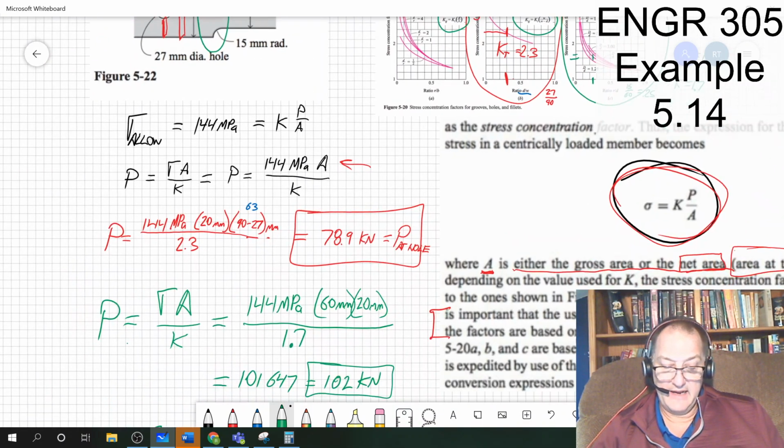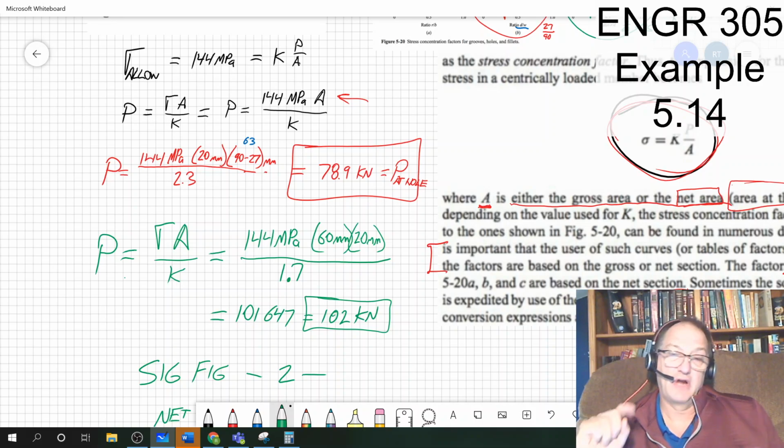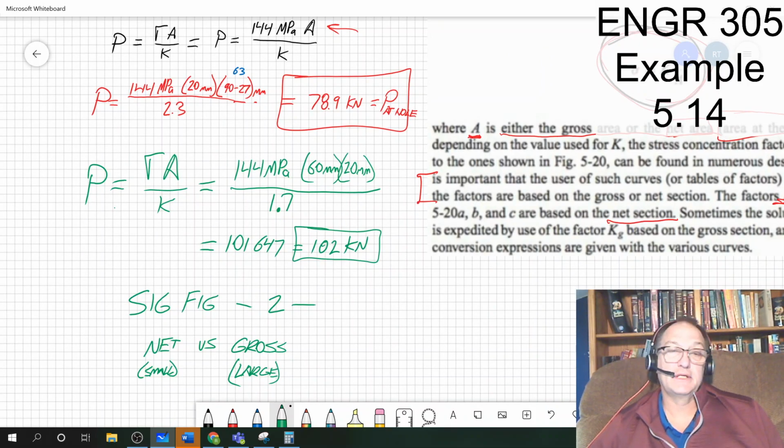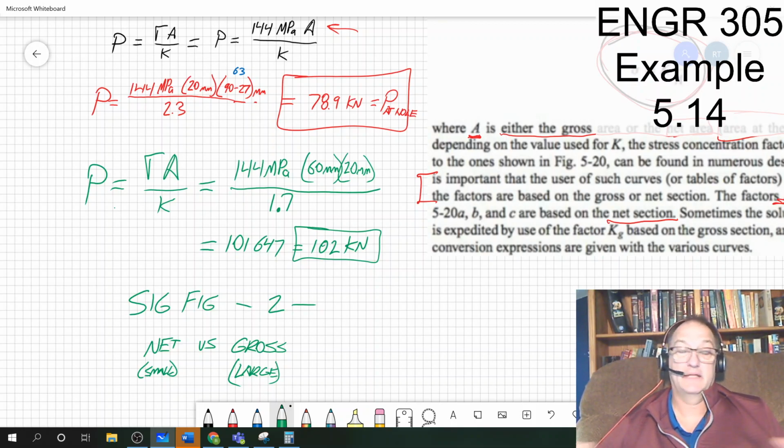We are going to have stress concentration factors for every type of load. So you should get comfortable picking the number out of a chart. There is a theoretical explanation, but there's not a theoretical equation that we can just apply and say, here's your answer. Instead we get these lookup charts to provide a correction factor, and we go with that.